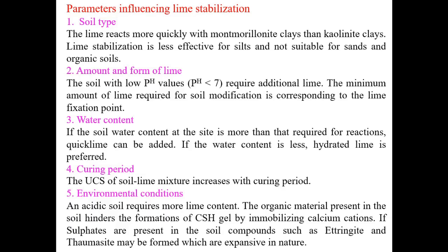Next parameter is curing period. Hydration is a quick process, whereas pozzolanic reactions are time and temperature dependent. The unconfined compressive strength of soil lime mixture increases with curing period. During the curing period, with the addition of water, the repulsive force decreases and density increases. If all the repulsive forces are removed, pore water pressure increases and density decreases.